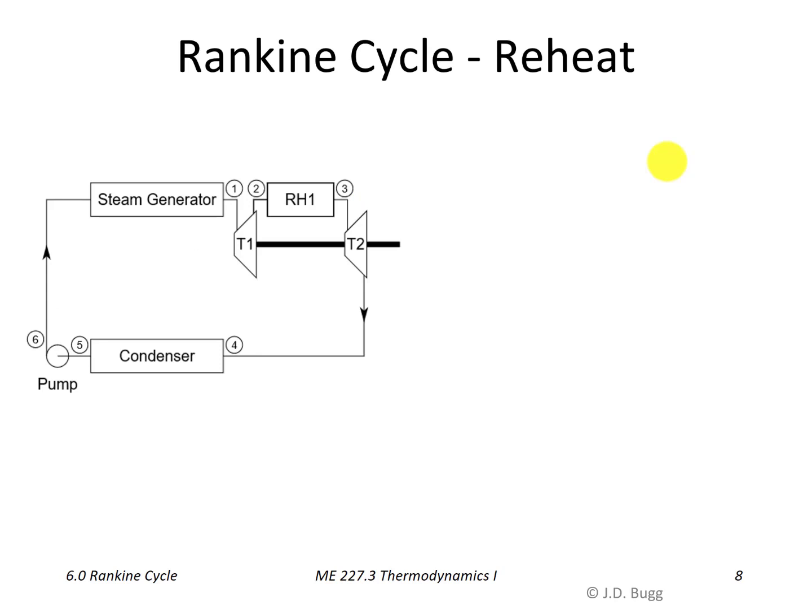So how does a reheater work? Well, we see the change here when we add a reheater to our plant layout. The condenser, the pump, steam generator, that's all the same. But instead of a single turbine, we now have two turbines. So this is called stage 1, and that's stage 2 of the turbine. And what we do is between the two stages, we add a reheater. And a reheater is just another name for a heat exchanger.